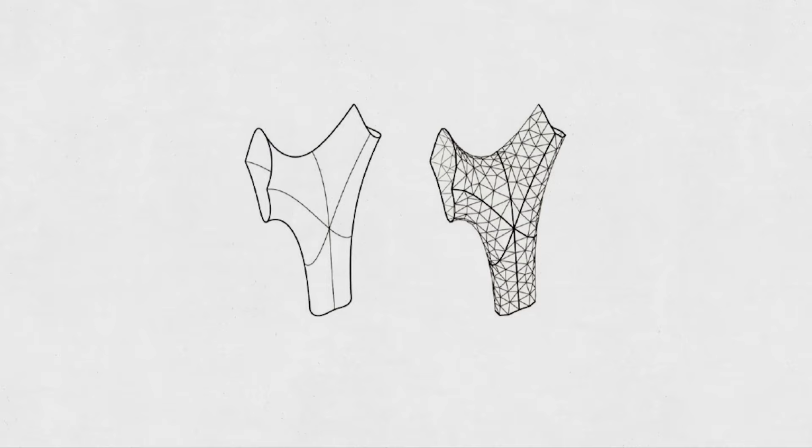The cool thing about NURBS compared to mesh is that it can create those intricate forms without losing any quality. Plus, it dynamically applies changes and has high accuracy for parametric design and real-world manufacturing. In this part, when you adjust the control points and parameters, you can see how the shape transforms smoothly and accurately. That's the main power of parametric design in Rhino.